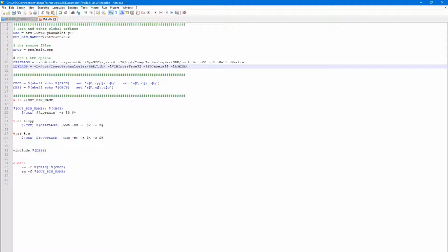Notice that when compiling remotely on the VisionSensor, only the VIB interface library is explicitly mentioned, as the others are automatically found and linked with each other internally. Instead, the cross-compiler needs the full specification of all needed libraries without exceptions. Remove echoes and sed commands, as these cannot be interpreted by the cross-compiler and would otherwise produce a reading error.